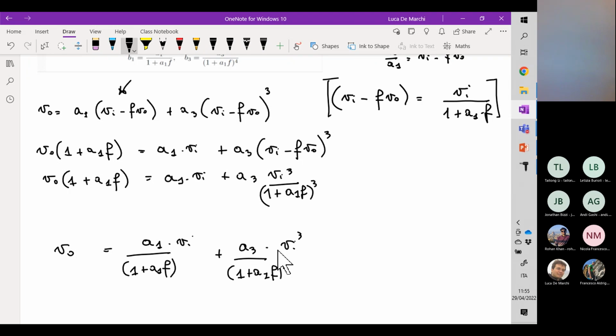So in this case, V out is given by, let's say, the output associated to the signal Vs is the input signal Vs times the chain of the two amplifying stages, so A2 times A1, this is the gain of the direct loop, divided by 1 plus beta times A2 times A1.